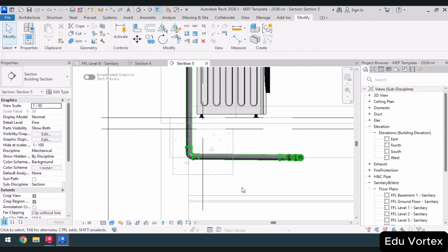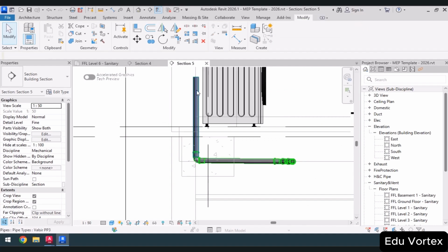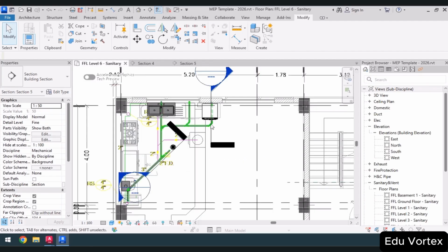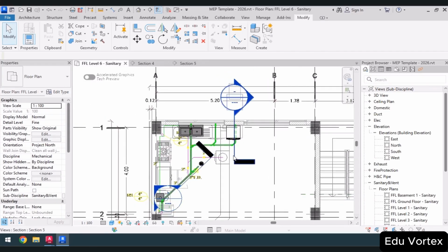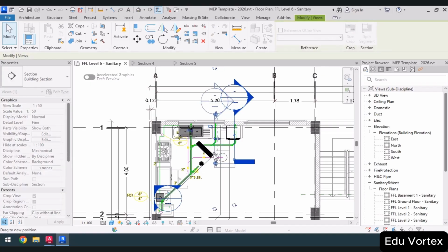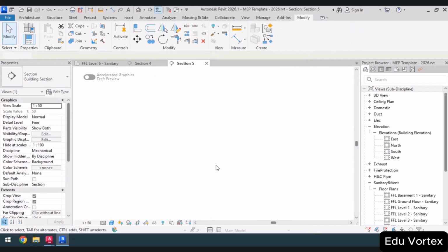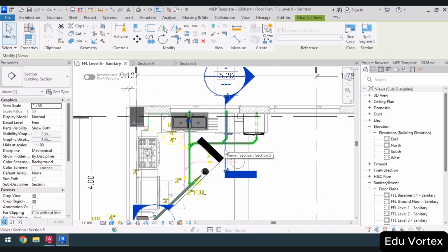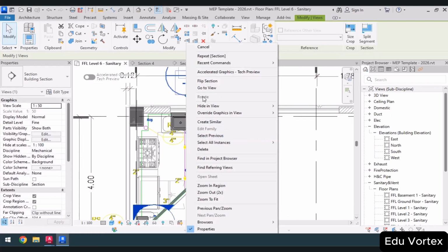I see that there is indeed a beam here, which means I cannot bring it directly through the beam and it needs to connect at a 45-degree angle. So this beam is present for both our sink and washing machine connections, as you can see here.